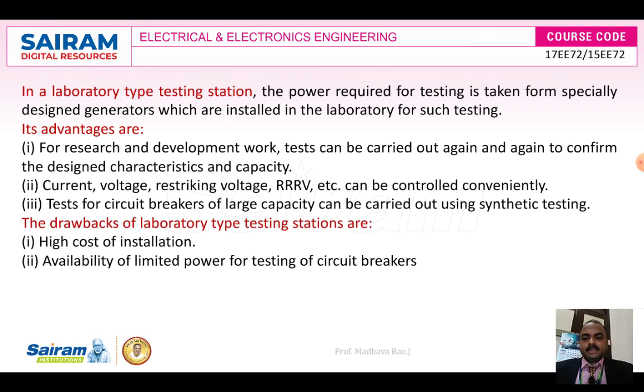Tests for circuit breakers of large capacity can be carried out using synthetic testing. Tests for circuit breakers of large capacity can be carried out, but in field testing we cannot, since it depends on the power station, but here we have a power generator. We have a separate generator. So those drawbacks in field type testing we can eliminate in laboratory type testing.